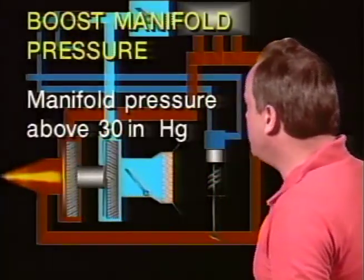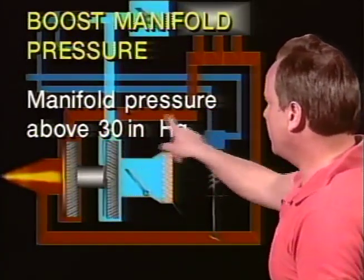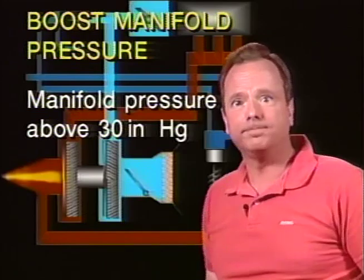Now, if ambient manifold pressure, ambient air, is 29, 30 inches, and you have manifold pressure higher than 30 inches, that is a magic word. That is called boost manifold pressure. It's manifold pressure above 30 inches of mercury.